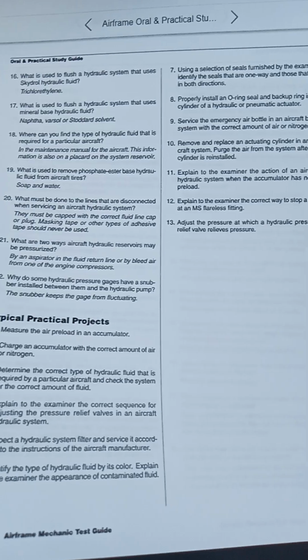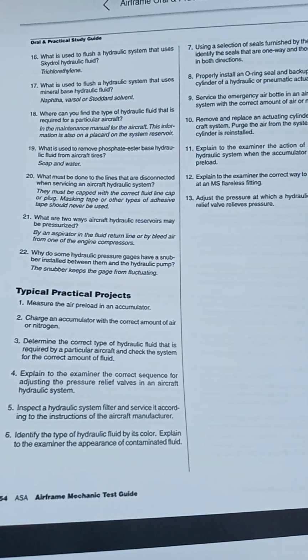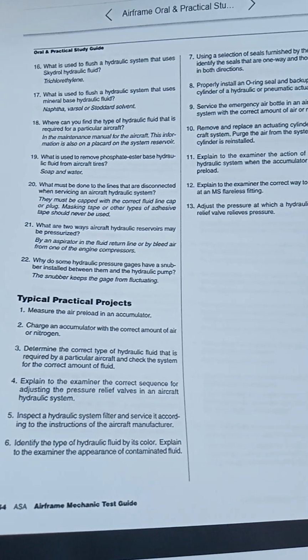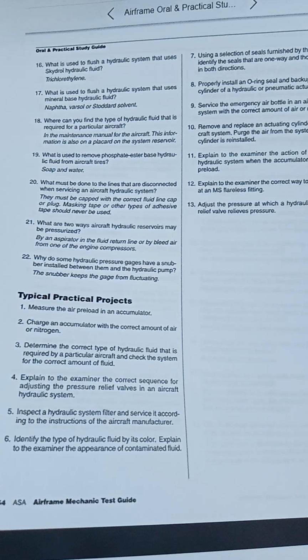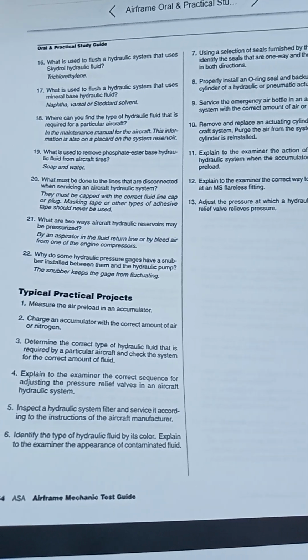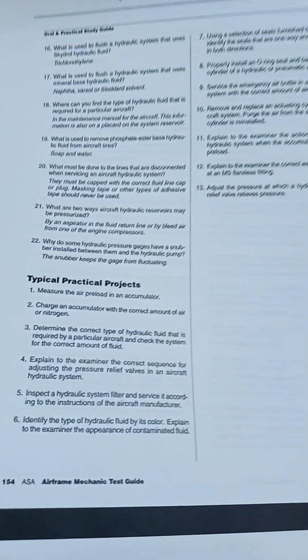What is used to flush a hydraulic system that uses Skydrol hydraulic fluid? Trichloroethylene. What is used to flush a hydraulic system that uses mineral-based hydraulic fluids? Naphtha, Varsol, or Stoddard solvent.